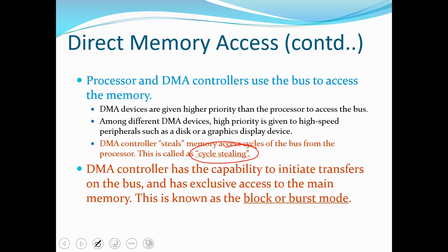The DMA controller steals or uses the memory access cycles of the bus from the processor. So that is cycle stealing.